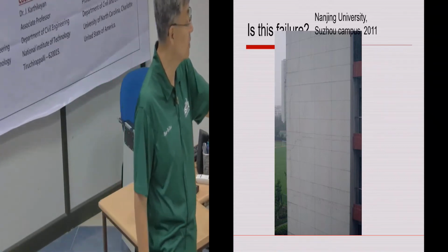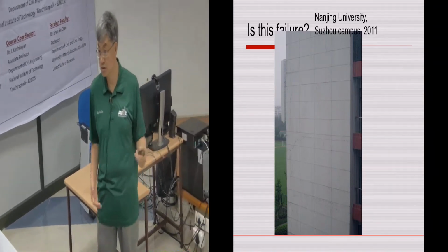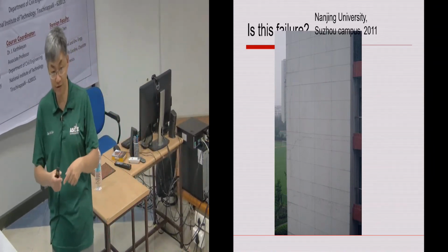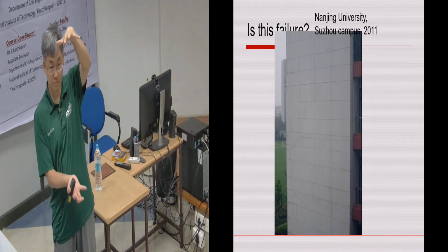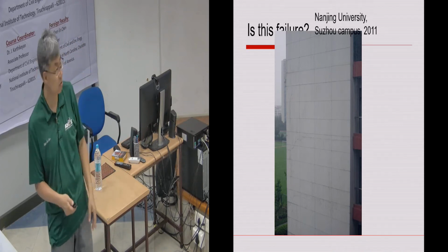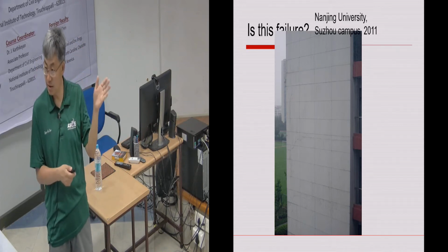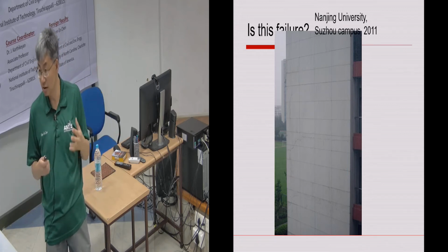Okay, and so those are very important. If the crack pattern would be more like a diagonal, then I would be very concerned, because diagonal failure may mean a punching shear kind of failure, or the wall has some kind of displacement. But being able to visualize this kind of damage is a learned process.